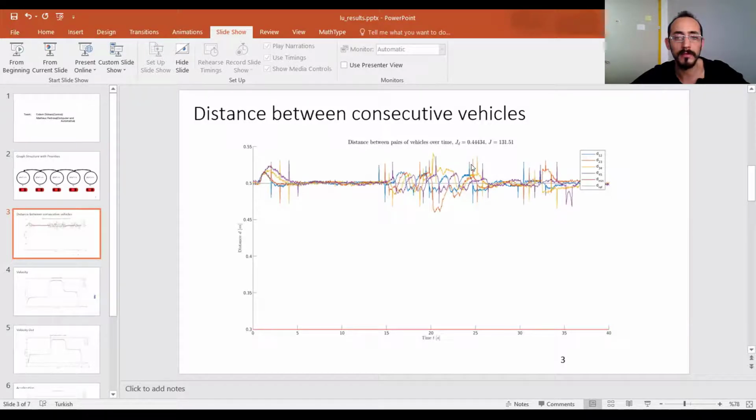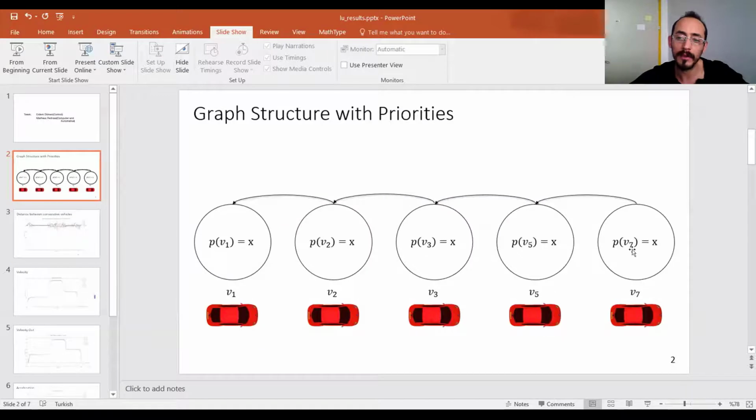In the first simulation we did, we just skipped the detail which we could not recognize at that moment. When we give the highest priority vehicle a reference trajectory, as you may remember, there's an error penalizer Q for the output error penalizing in the MPC formulation. We just forgot to make it 0.